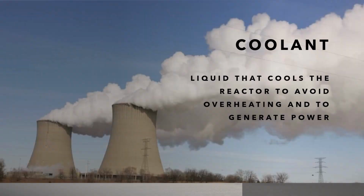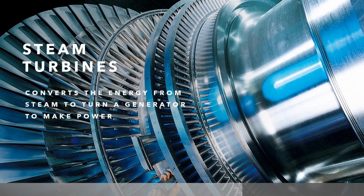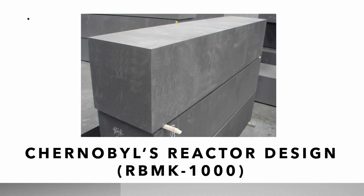Fission gets really hot, and so the fuel rods need to be cooled down in order to avoid melting the core. Some sort of coolant is required for this. Usually water is used. If the moderator is water, that can also act as a coolant as well. Steam generators are required in most nuclear reactors to turn the pressurized water into steam to power a steam turbine, which is hooked up to a generator to make electricity.